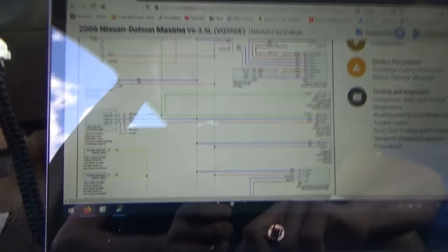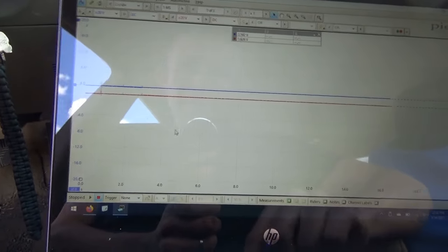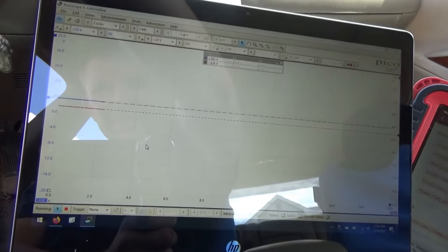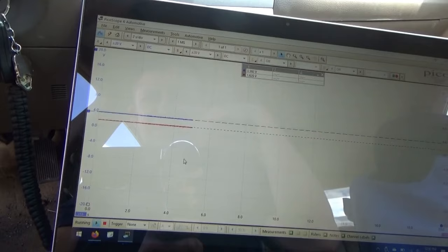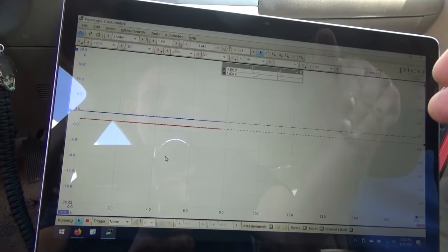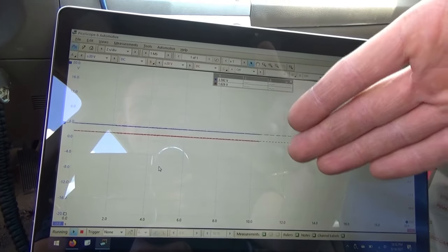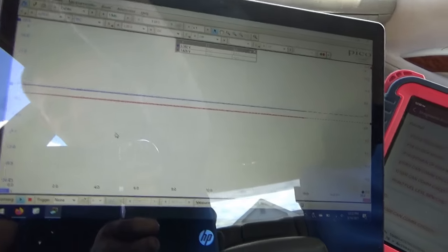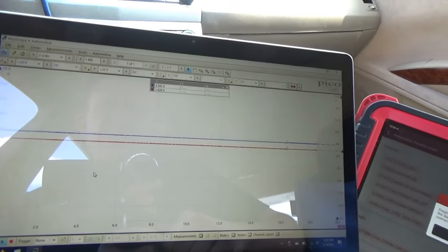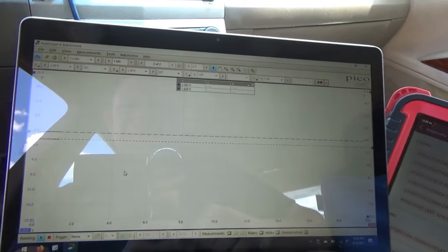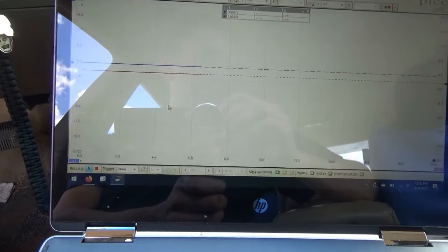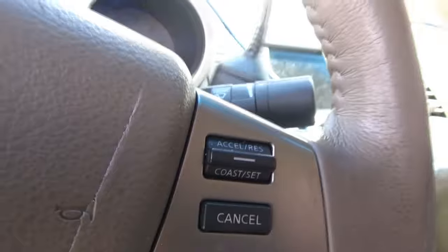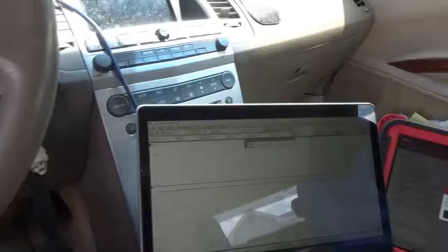Very interesting symptoms. When we turn the key off, no change to the CAN whatsoever, and the voltage levels are not pulled to ground or stuck at battery voltage. There must be a module just keeping these lines low, or something's not waking up. We can plug in our scanner into the BOB and see if it tries to talk on the CAN.